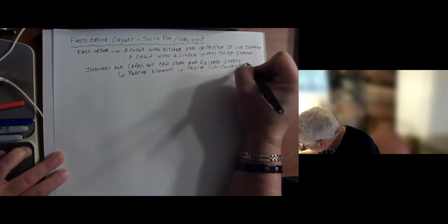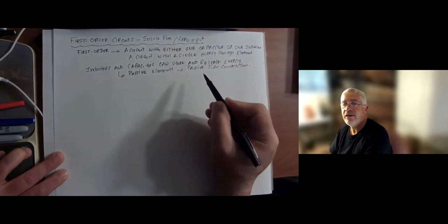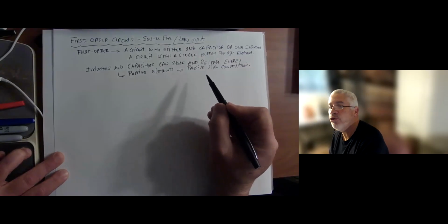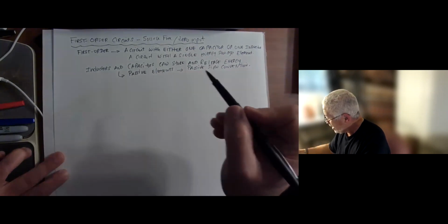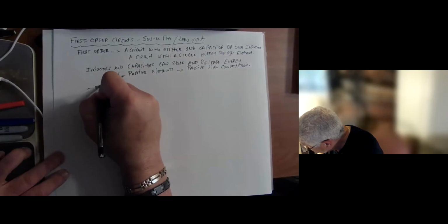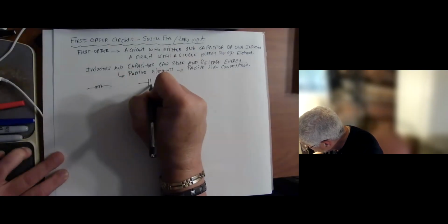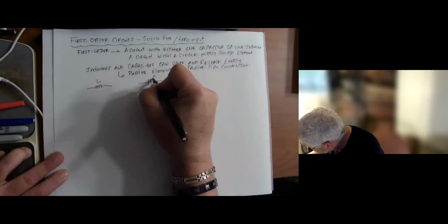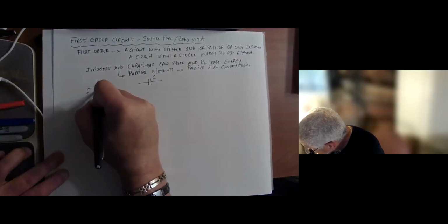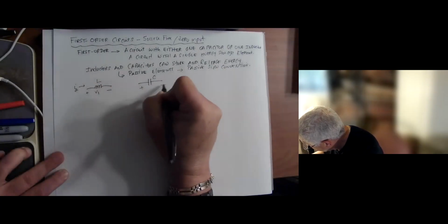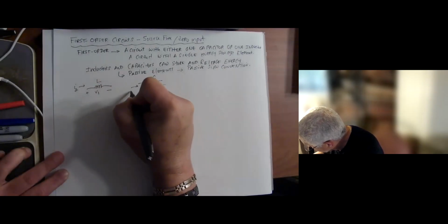When we talk about the passive sign convention, we're talking about how, when we write the voltage-current relationship, we need to make sure the current is entering the positive terminal of the voltage. Just to be complete, we're talking about these two elements. Let's put an inductance here, a capacitance here, and then a voltage V1 and a current I2, V3, I4.